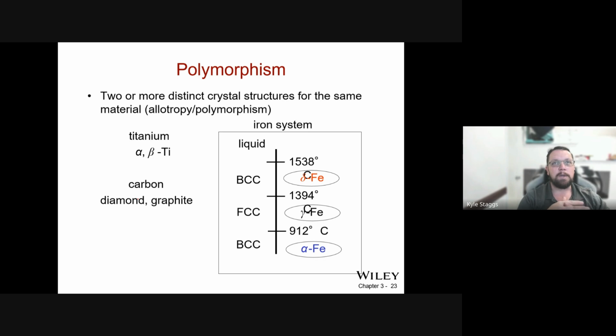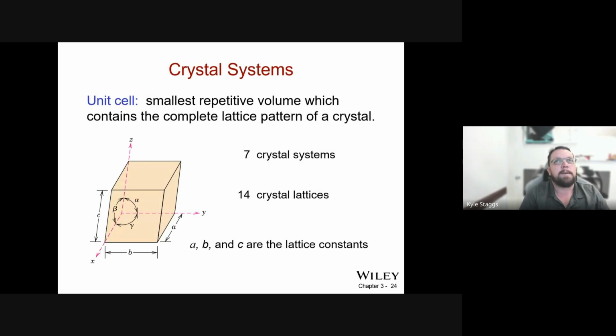So you have liquid iron typically somewhere in the range of 1600 or so C, which is really, really high temperature. You have multiple different types of crystalline structures. Even though it alternates back and forth between body-centered and face-centered cubic, you're having physical changes in the crystals until it becomes a liquid. And then it's completely amorphous and it is no longer the same.